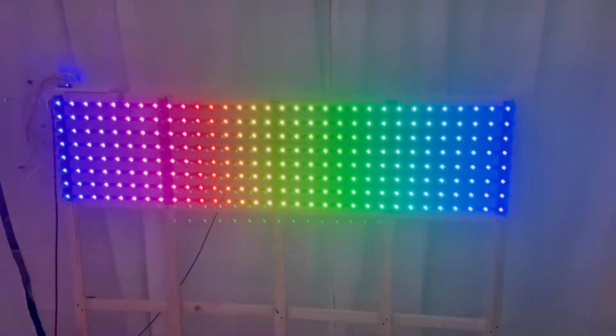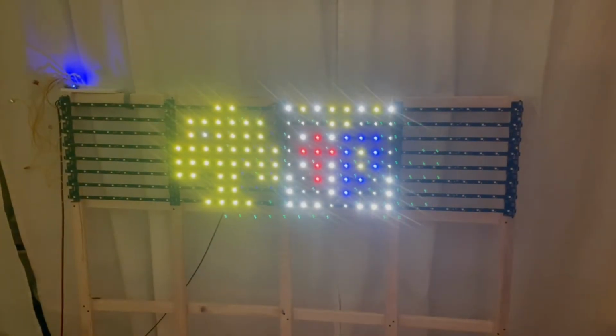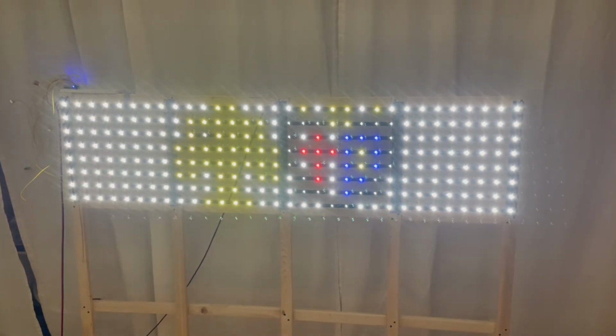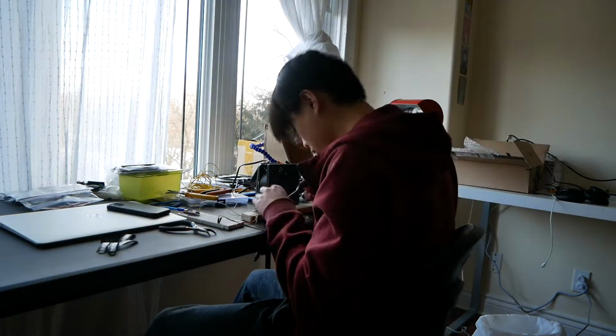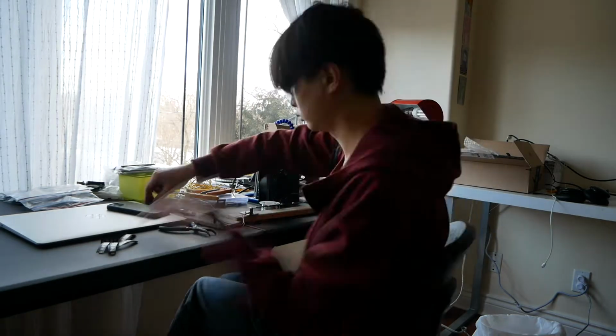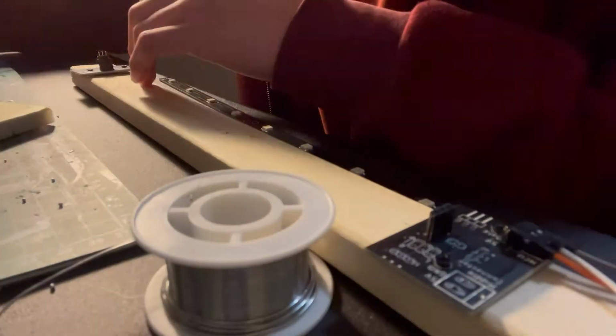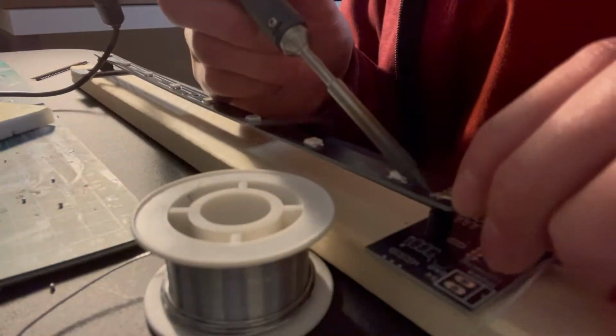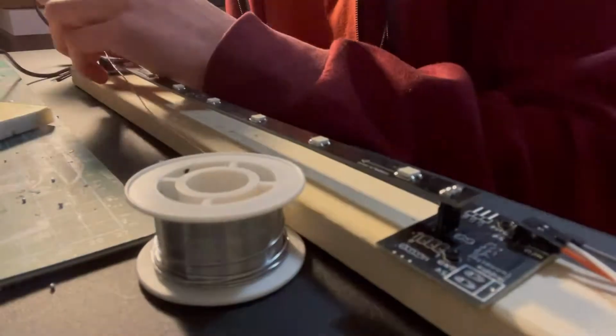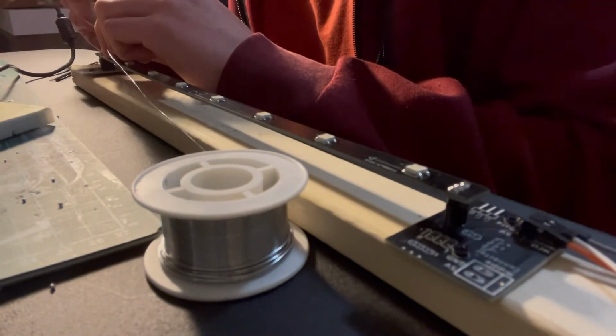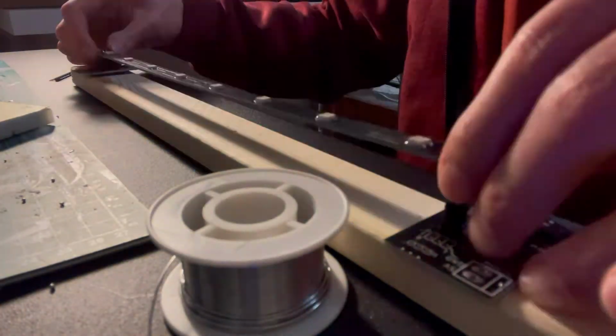I also managed to program a few effects as something to show for my upcoming school presentation. After that, it was time to repeat the process 2 more times. But to make sure I was soldering the LEDs correctly, I mounted some connector boards, put male headers in, and soldered the strip directly on, where I tested each of the color components with some test patterns.